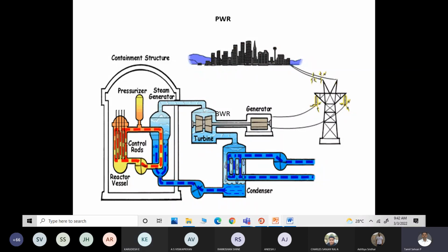It is a pump. So when we use a pump, the pump pumps the water, the pump pumps the hot coolant. So it creates a circulation, or a certain velocity is imparted to the hot fluid, and similarly a certain velocity is imparted to the cold water. So it is an example for forced convection, not natural convection. Is it fine?